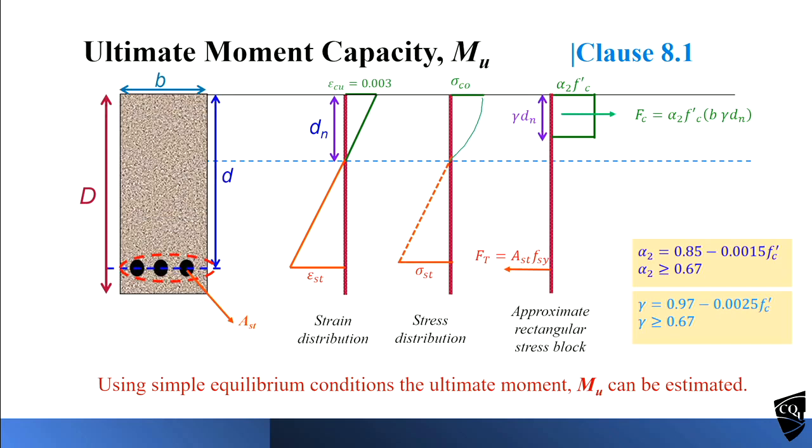Okay. So now we will see how to calculate the capacity, because we know how to get the maximum bending moment. We need to know how to calculate the bending capacity of the concrete beam with the reinforcement, so that we can see how much steel we need, because if you increase the steel, the capacity will increase. So let's assume we have a beam with the reinforcement at the bottom side. Bottom is the tension, top is the compression.